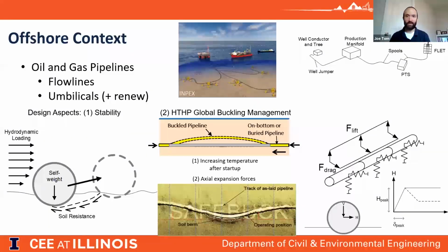So in both of these cases, the pipeline engineer will take a typical structural model where the input from the geotechnical side will be a kind of spring. That might be an elastic plastic spring where we've got a peak. Can you see my mouse there? Yes. Yep, you've got a peak capacity, and then that might be plastic, or you might have a trilinear spring where you have some softening.